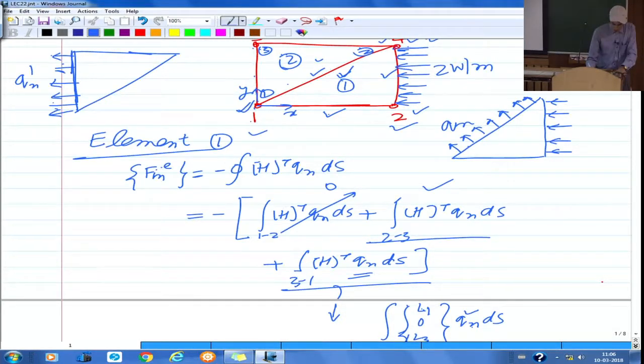Because here you are prescribing a temperature, wherever you are prescribing a temperature there will be some flux. But whatever heat flux is coming from this side is actually going to enter here. So you will have the same variation whatever you have here, and here Qn is 0, but the magnitude is the same Qn whatever you have here, and let us say I have said that this is Qn dash.